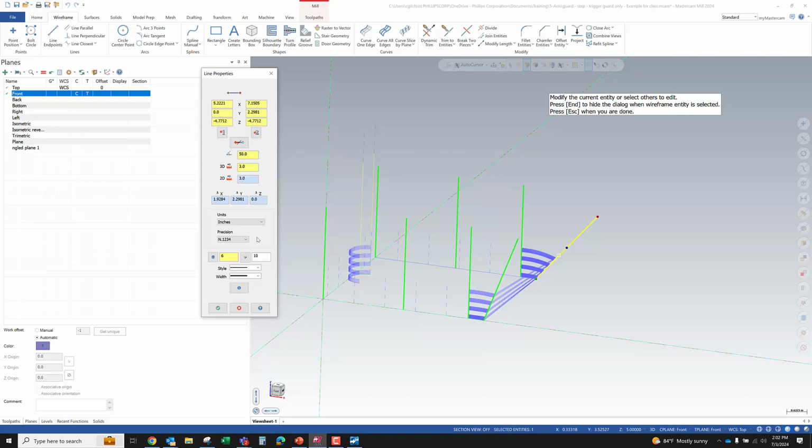I would say the minimum here is millionths, 6 decimal places. You get a pretty good idea of what's going on, right? Because you can say, okay, in my code, I'm getting 5.2221, but there's still 28 millionths. It's less than 50 millionths, so it's going to round down. So that's why I'm getting that number. But there's still these remainders that are left over, and this precision is critical when dealing with arcs.